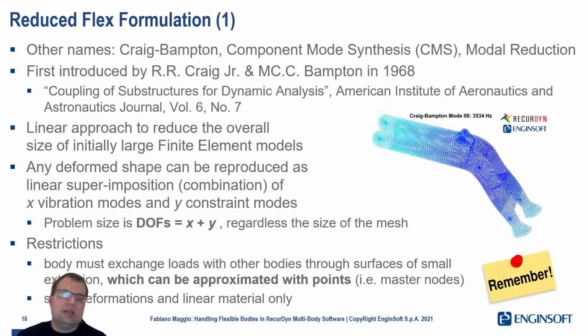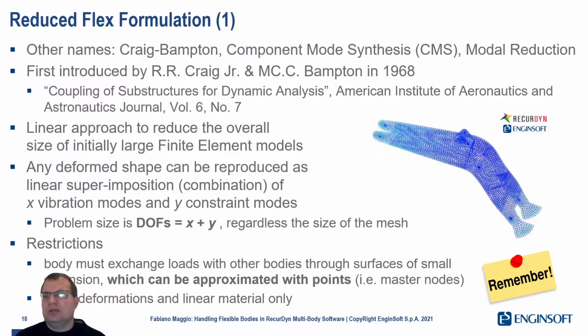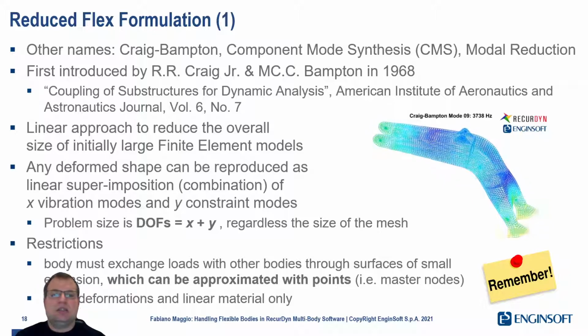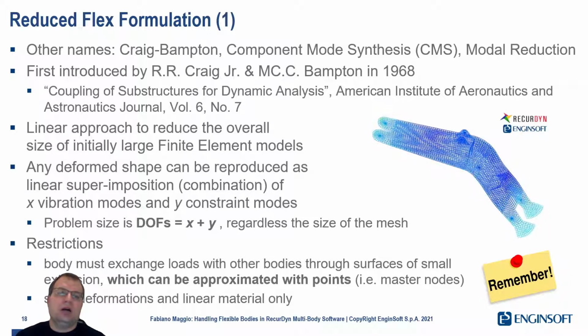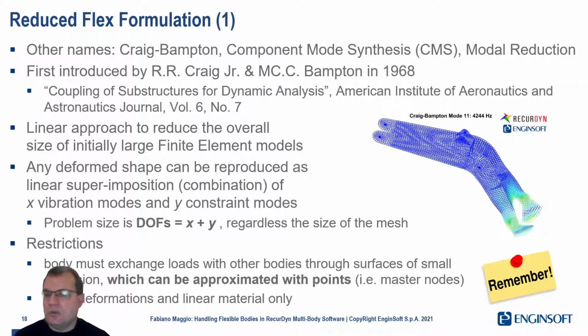And the theory is a linear theory. So the assumption is that the deformation of a body can always be expressed as a linear superimposition or linear combination of vibration modes, I set X for the number, and constraint modes, I set Y for the number.